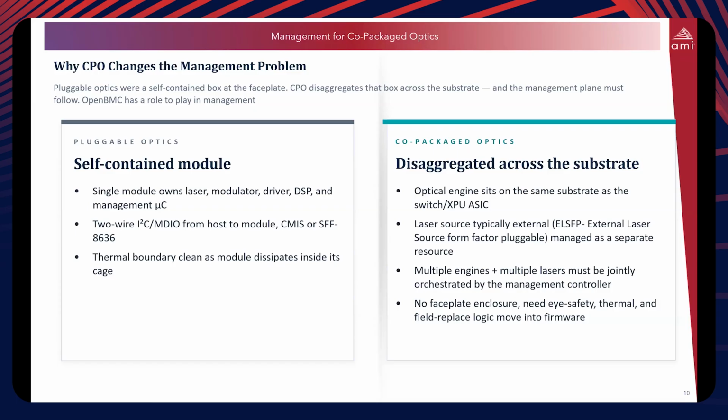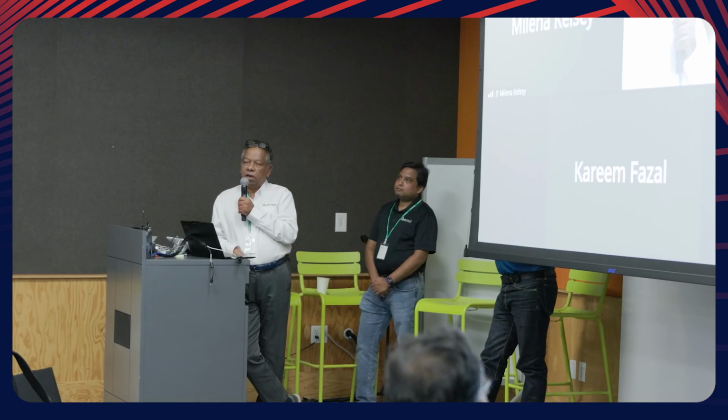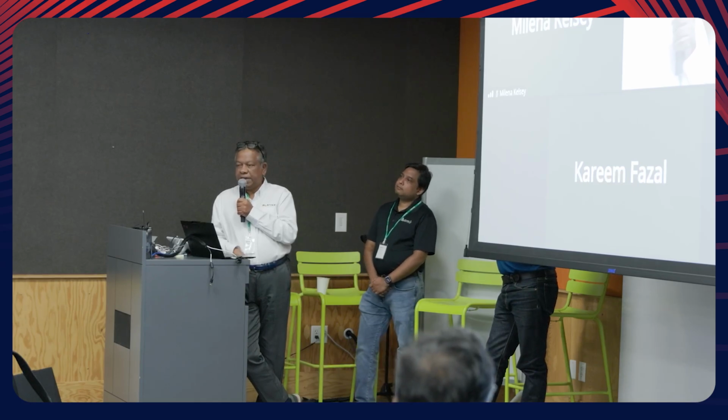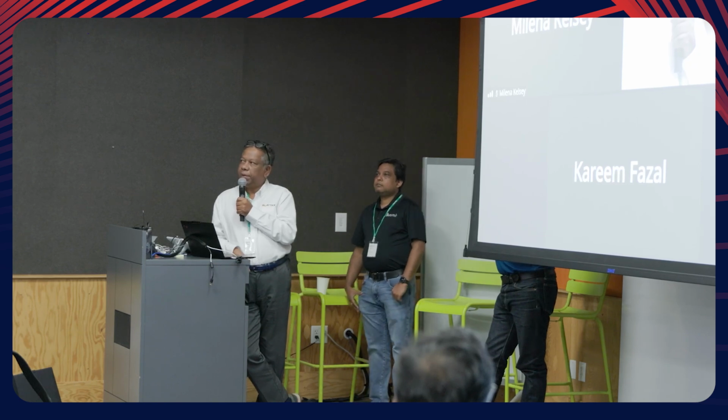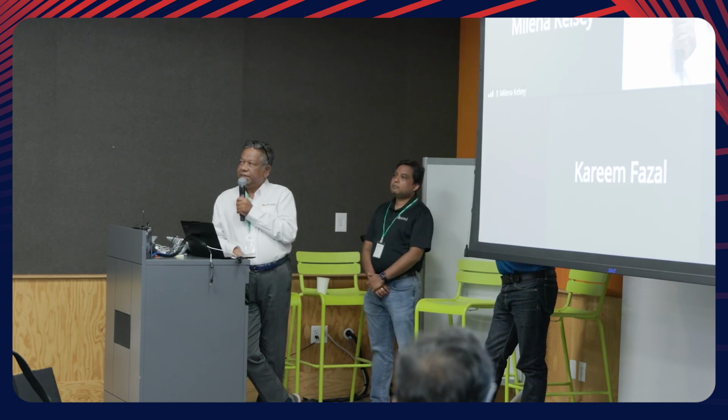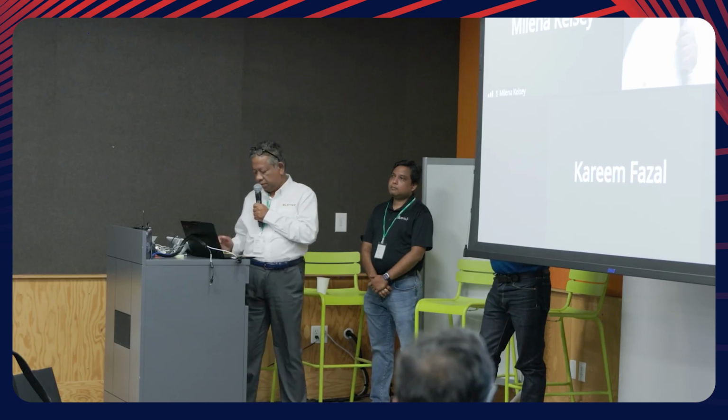And if you look at this today, this concept is pretty much new because we see a laser coherency problem caused by temperature. If there is temperature variation across the room, you may see this coherency issue with the laser. You may see the wavelength change slightly. When you talk about that kind of speed, that's a significant change. There is a lot of error correction that we see today. Safety is another concern. So this is how co-packaging changes the management problem.